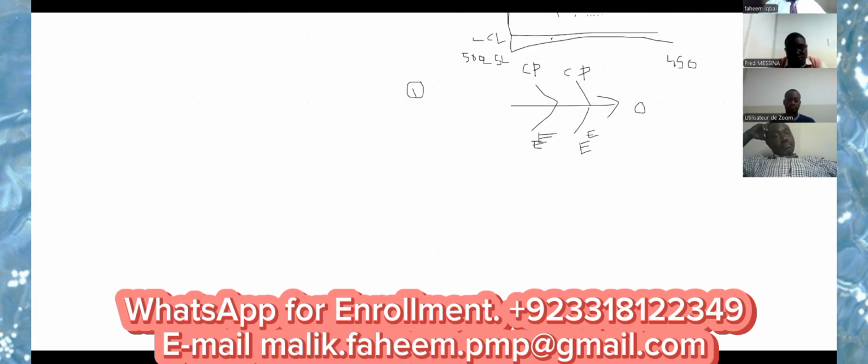For example, we got the contract of 1000 joints and we cannot perform the inspection of each joint. For that purpose, we need a big team, we need tools to perform the inspection, and we need time to perform the inspection. There we will use statistical sampling. After every 100 joints, we will take one joint and perform the inspection. If the inspection of that joint is okay, then we will consider the rest of the joints okay, or 99 joints okay. We will perform this at every 100 intervals or every 50 intervals, like that.